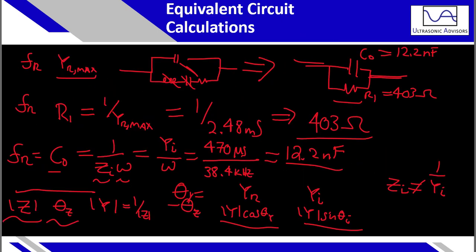I just need to make a quick correction here, and I'm leaving this in because we can all learn from mistakes. When I calculated the capacitance, that is a static or parallel or intrinsic capacitance, we can describe that with many terms. Some are more accurate than others in certain cases. But that discussion aside, the frequency here should be used as an angular frequency, so we really should have a 2 pi factor here. And this then leads to this number becoming